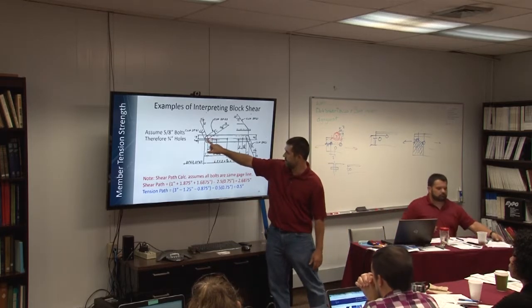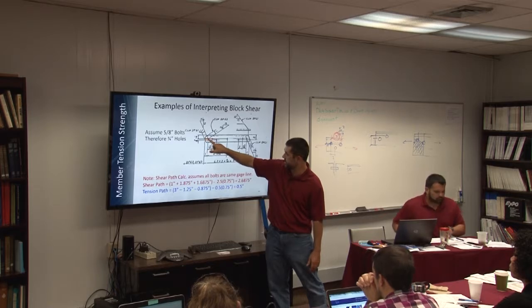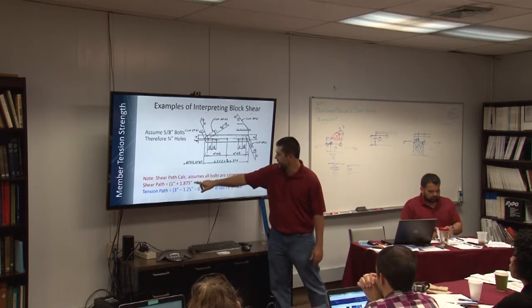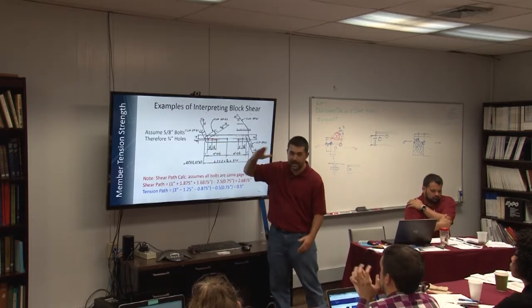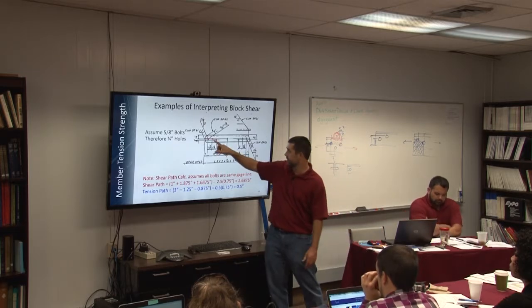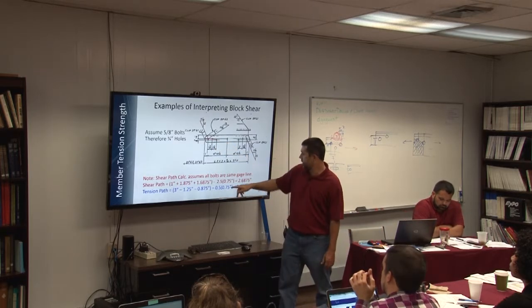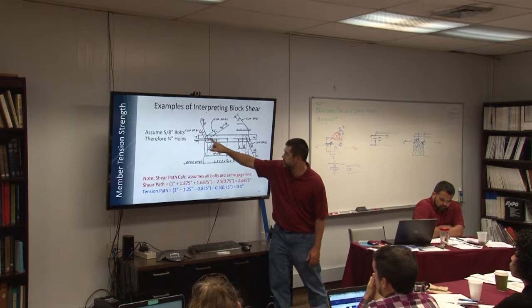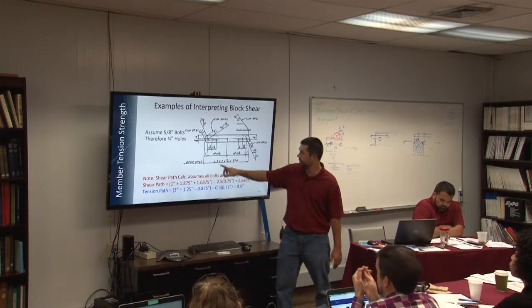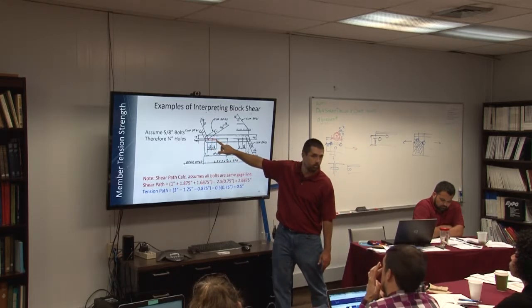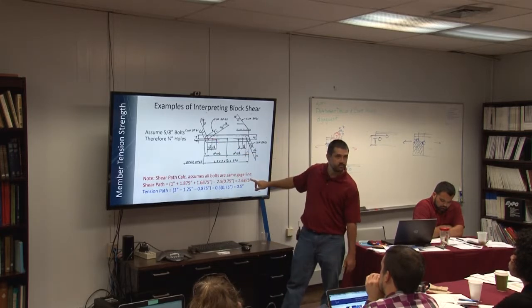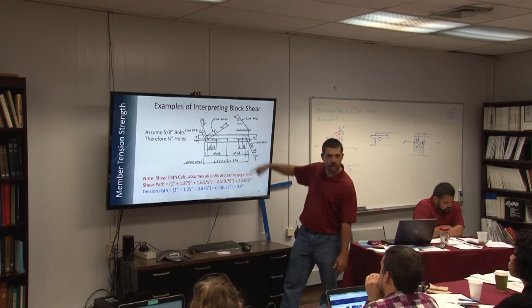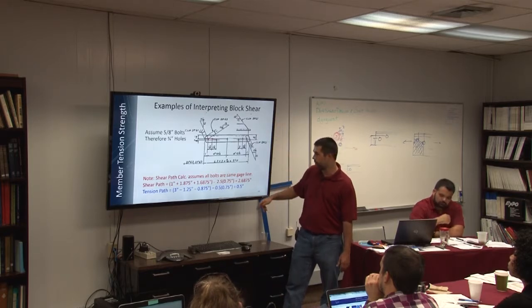So it's going to be 1 inch on the end, that's the distance from the end to the center of this bolt, 1 7/8 of an inch from bolt to bolt, 1 11/16 from bolt to bolt. I'm not going to add anything for the diagonal, I'm just going to be conservative. And then I'm going to subtract 2.5 holes. Right? 1 hole, 2 holes, and a half a hole. And I get 2.6875. I can input that into that column on the right in my member table.